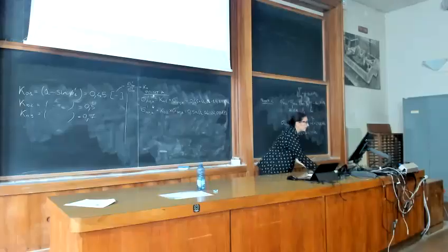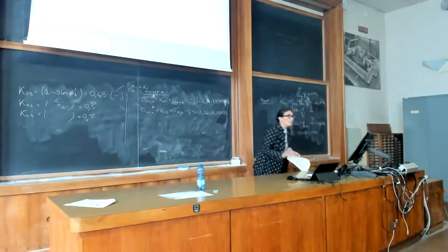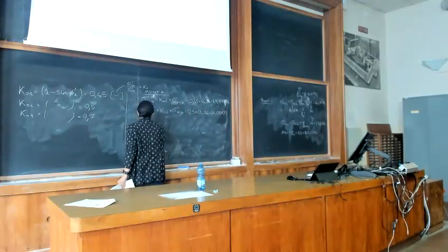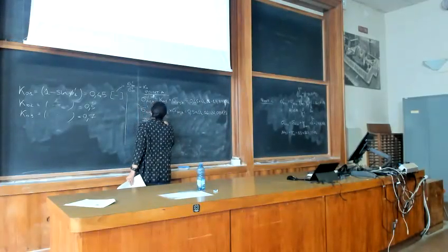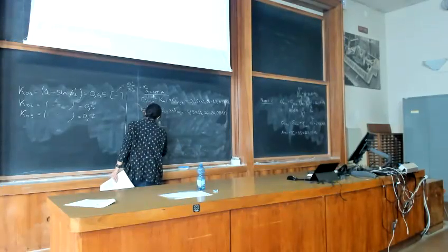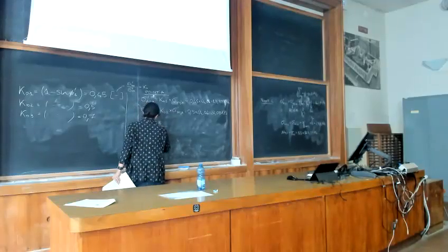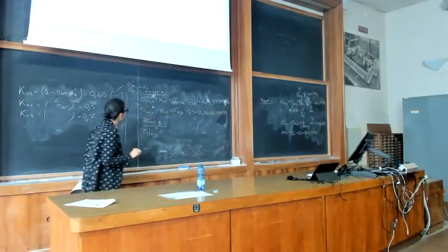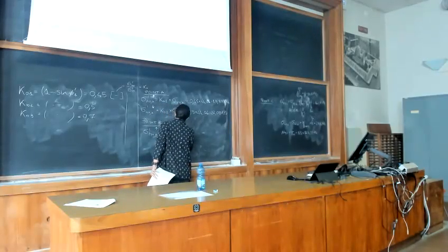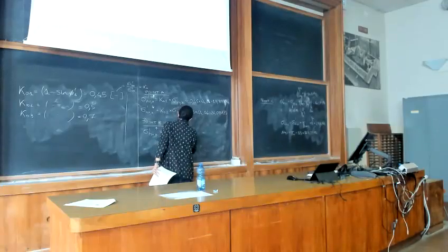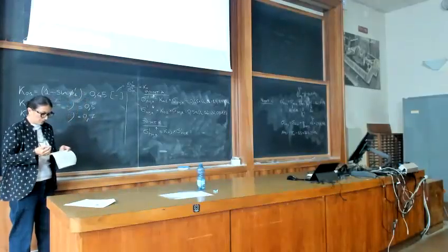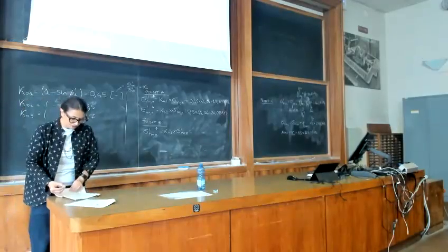Okay, we do the same going down at the interface between sand and gravel. So we are in point B. And we have sigma dash H naught in point B above the interface, and we have K naught 2, which multiplies sigma dash V naught in point B. So 0.5, which multiplies, let me go to the calculation to provide values.